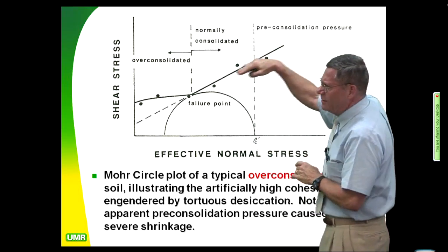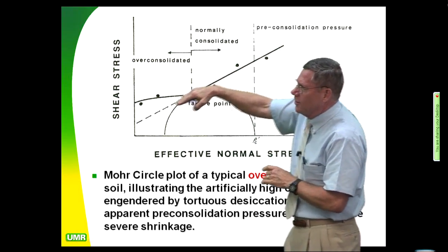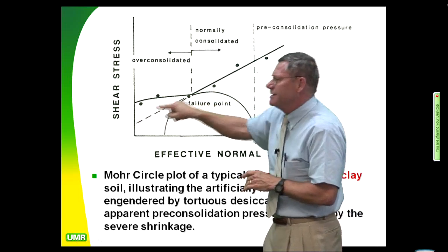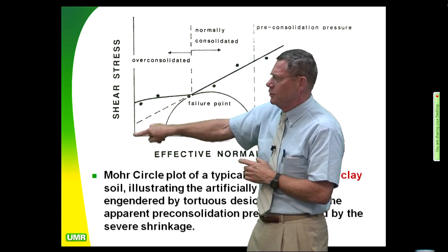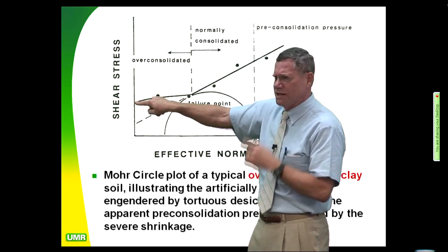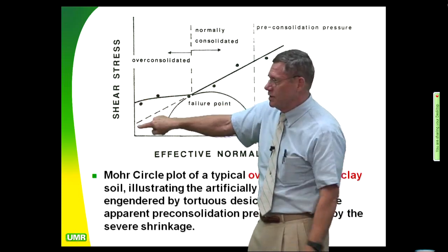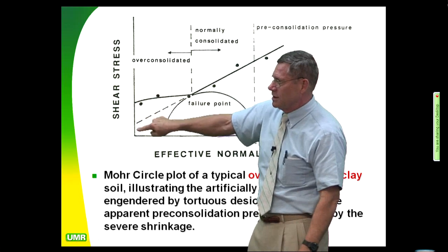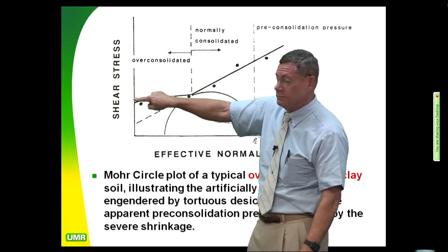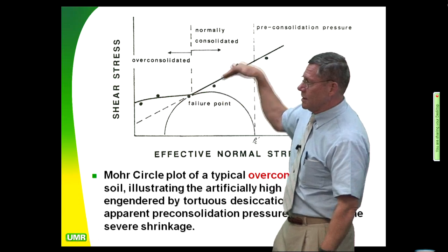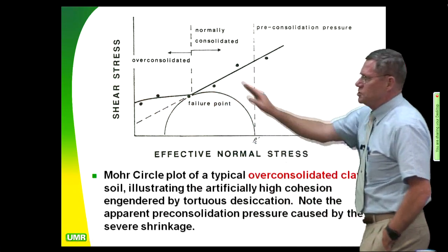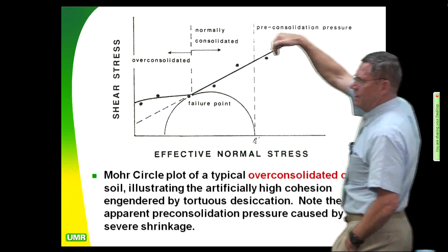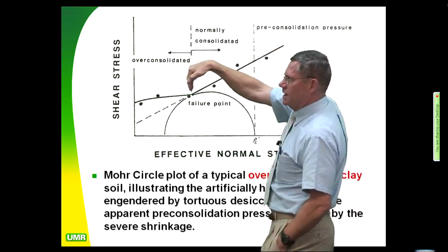So it's going to come down, and you're going to take this line, and you're going to go, oh, there's a cohesion. No, that's not the cohesion. If it's overconsolidated, there's a cohesion. It's got big cohesion. Remember those dirt clods that hurt Dave's head? That's the big overconsolidation. So I'm going from this strength, going up 3 times, 3-fold higher. So I'm coming down here and then skating across like that. So I'm normally consolidated from here on up. I'm overconsolidated here on down.